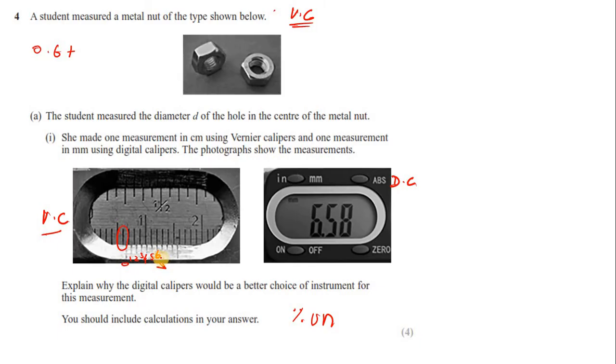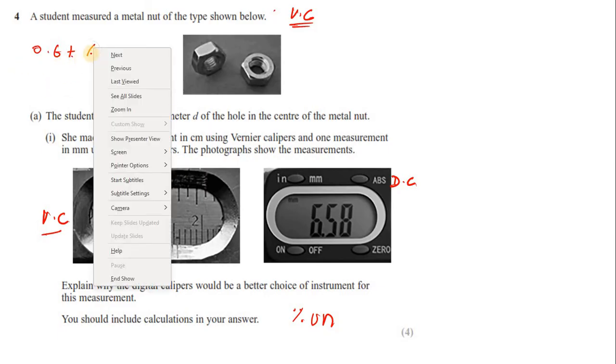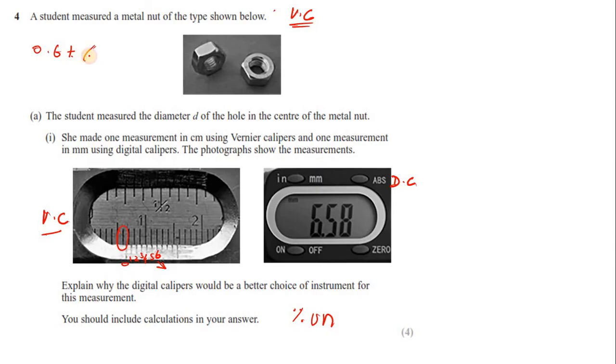So the overall reading will be 0.6 plus 6 into least count. And the least count, or you say the resolution, is 0.001.